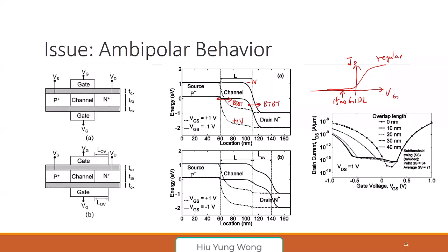So both of these contribute the current, which is not good. We don't like that. Because in a CMOS, your N-type is going to experience negative gate bias to the source in some instance. If that is the case, then it is not off. You are going to have leakage.